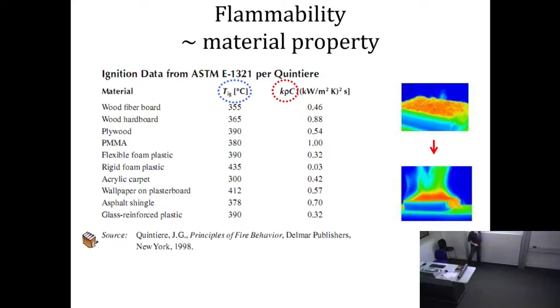And which one is that one? Well, it's a little bit moved, isn't it? Yeah, perfect, the foam. So if you look into its table, it's like, oh, my foam is fantastic, I'm going to sell it like crazy. I'm going to tell all my customers my foam is really difficult to ignite. But I'm not going to tell them that the heat transfer of my foam is absolutely crap. Foams are insulating materials. That means they don't want to share their heat, they don't want to conduct it away. That means they actually behave particularly badly in fire.